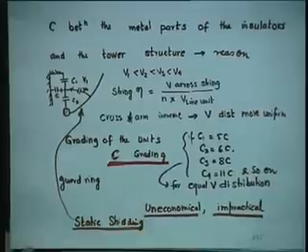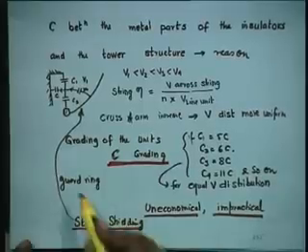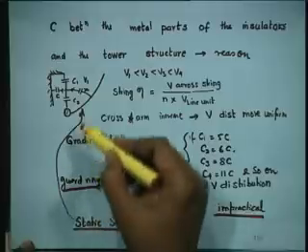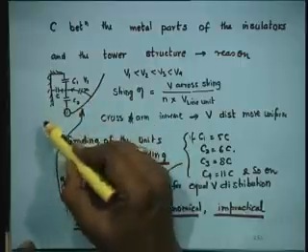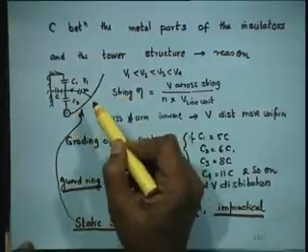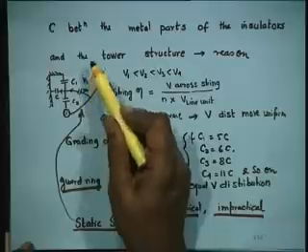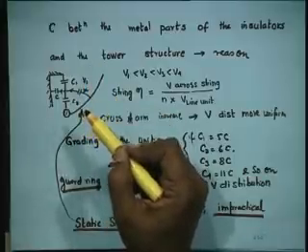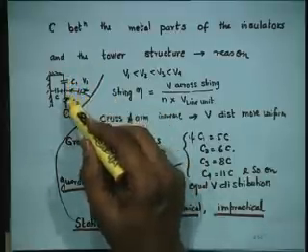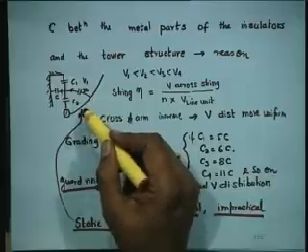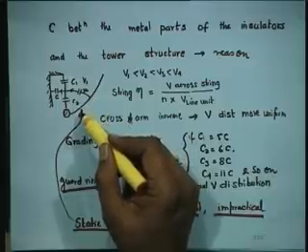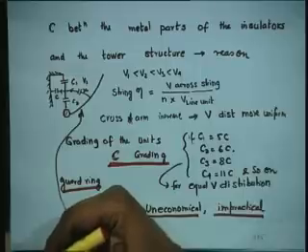Another method is called static shielding, using a guard ring. This is a guard ring, and you have connections here. Whatever values of x, y, z you compute will see to it that the voltages are exactly equal. This is much more practical than the earlier method, and this was being used in practice.